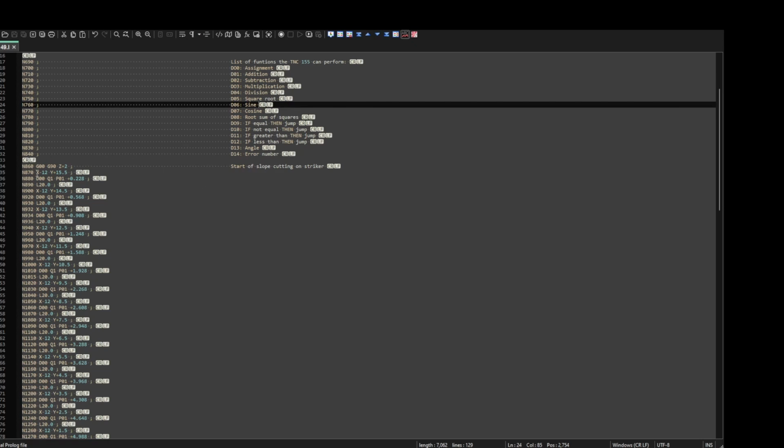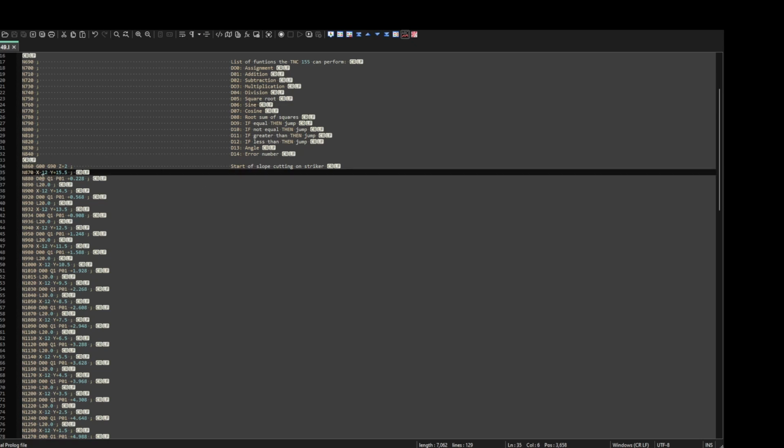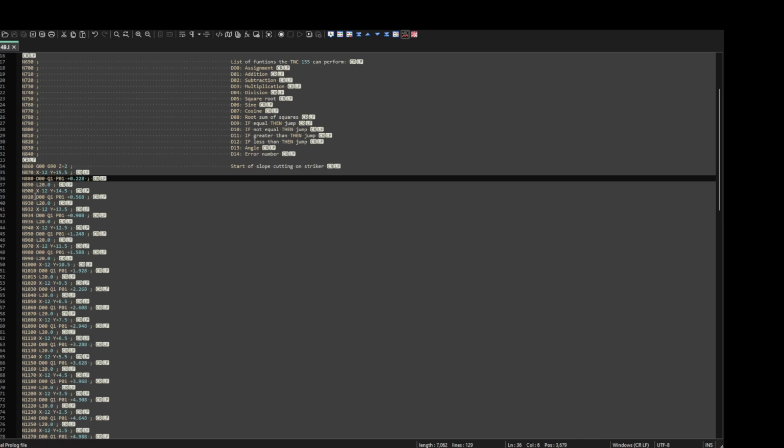And what I'm doing here is I'm setting the cutter at where I want the beginning of the slot to be, minus X minus 12. The slot's set in the function down below, but you can see here, this is where I want the initial Y position to be, plus 15.5. And then I do this parameter programming. And you can see here it's saying D0, so I want this line here to assign a number. And it's going to put the number in Q1.